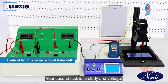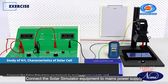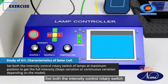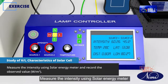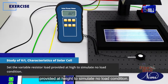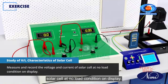Your second task is to study the voltage, current and characteristics of a solar cell. To perform this task, you need a solar simulation lab. Connect the solar simulator equipment to the mains power supply and switch on. Set both the intensity control rotary switches of the lamps at maximum position to get the full intensity. Measure the intensity using the solar energy meter and record the observed value. Set the variable resistor load to high to simulate no load condition. Measure and record the voltage and current of the solar cell at no load condition on the display.